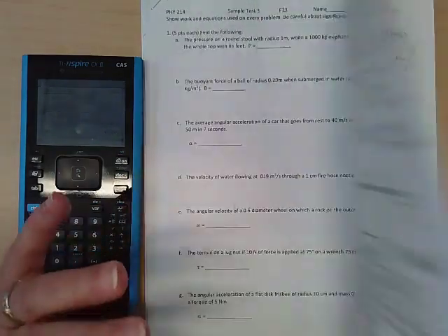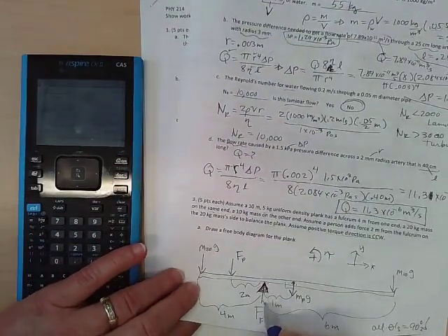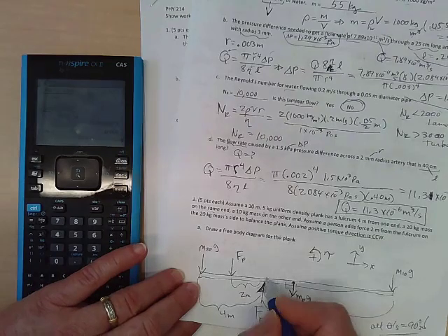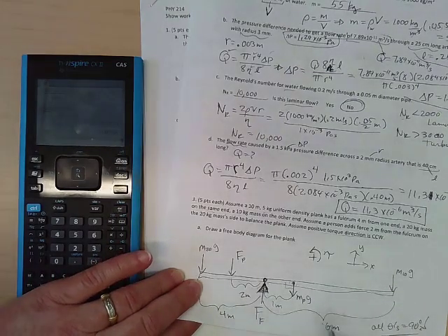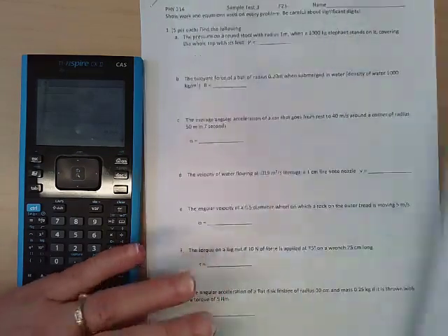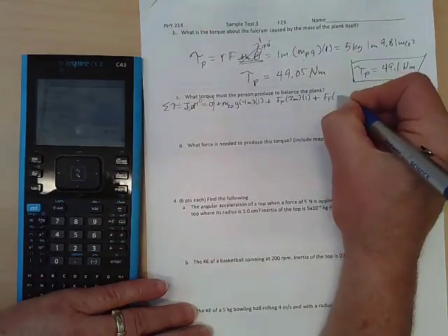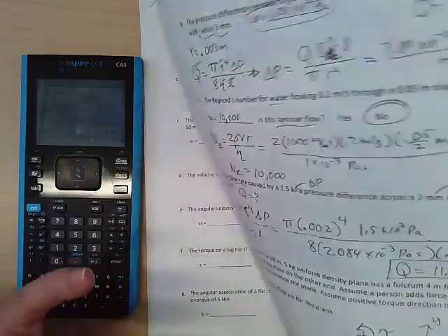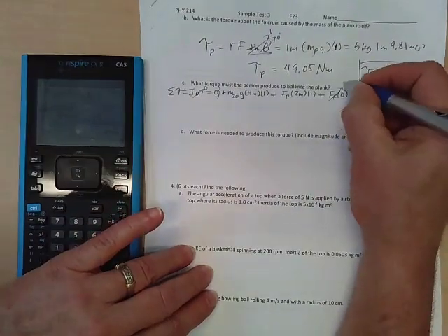And then next torque. So let's look at this force of the fulcrum, it's operating on the pivot point, right? So I guess we can go ahead and include it, but we've got a force, F sub F, times the moment arm, which is 0, right? Because the distance to the pivot point is none because it's on the pivot point, so that torque is really just going to go away.